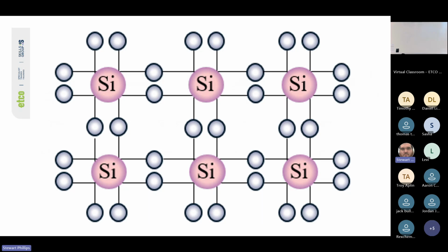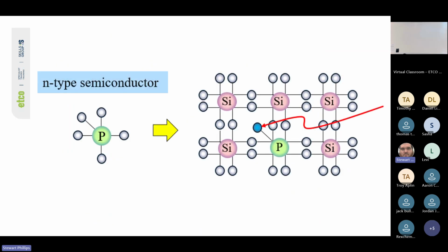So when we're talking about the crystalline structure of silicon, this is what we mean. As you can see, there are 2 electrons between each silicon atom. If we look at the 2 on the left, the top and the bottom one each share one of their own electrons with the other, making a pair. So this would be a stable insulator because there are no free electrons to move and no holes for the electrons to fill.